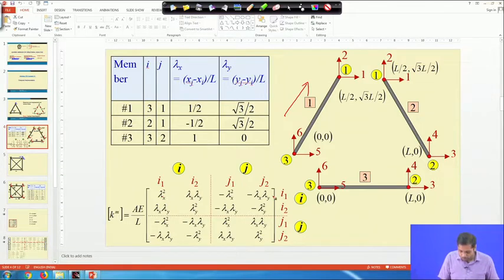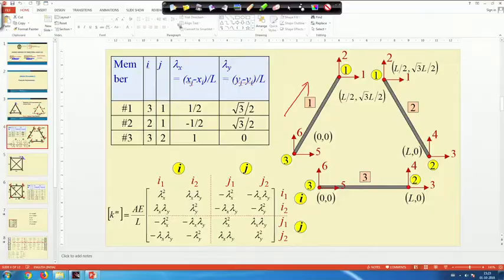And these 4 columns, because these are 4 by 4 matrices, because for a given member we have only 4 degrees of freedom. Okay. So, whenever we have a problem, we create the model, and the first thing we have to do is identify and give the coordinates of the nodes. For instance, in this problem we have 3 nodes.